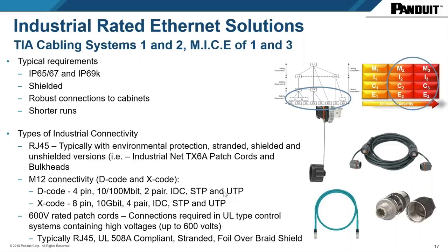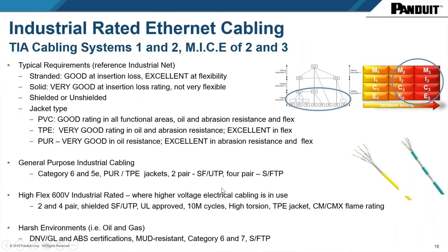So at some point in this presentation, you will see that different style jackets, for instance, are used at different points. So choosing if you need to use a PVC or a TPE or a PUR type jacket for a certain cable is important when you're running these cables through chemicals and so forth. So you look at PVC and you say, okay, it is good rated, it has some abrasion resistance and so forth.